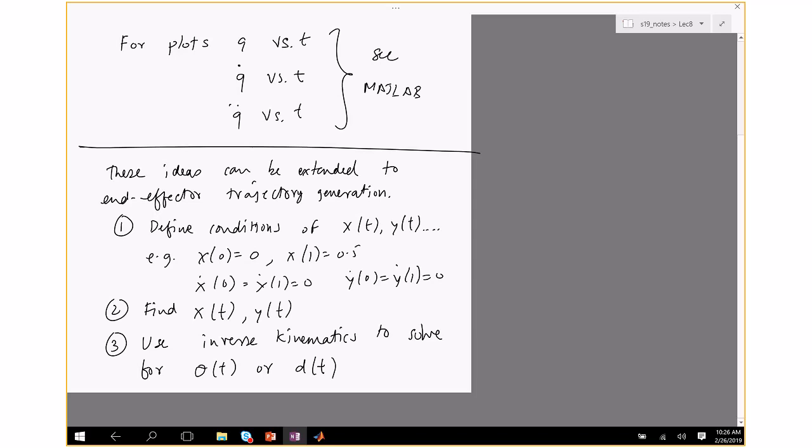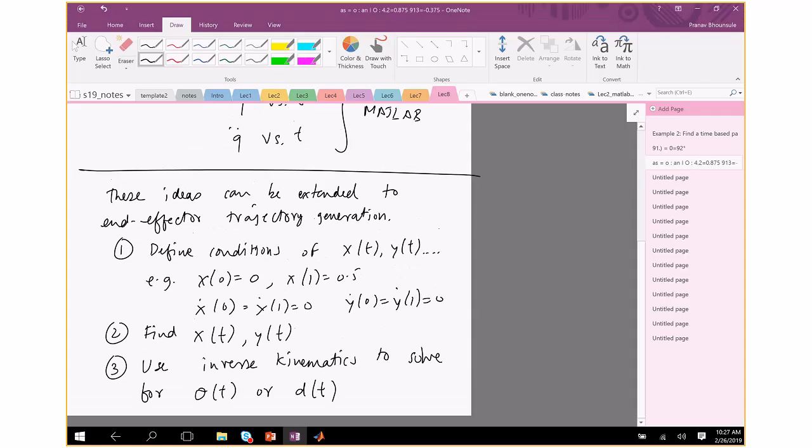Because in inverse kinematics, you specify the end effector, which is your trajectory, but you eventually have to control the joints. You can only control theta, you cannot control the end effector directly. So you have to do the inverse kinematics that was shown, drawing circles and so on. You need to map it to the theta and d using inverse kinematics. For that you need the DH table. If you remember, we used fsolve to do that. Now a few comments about inverse kinematics.